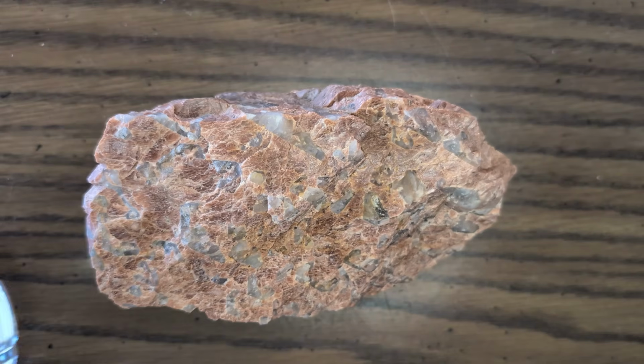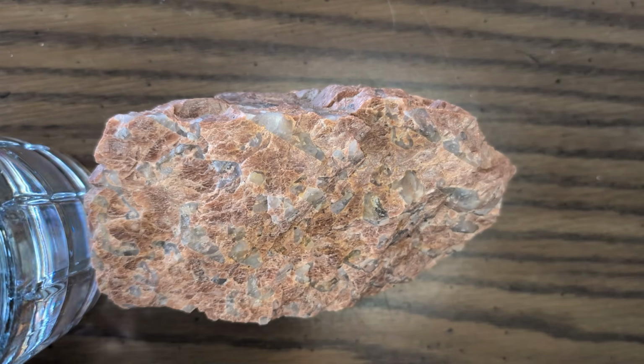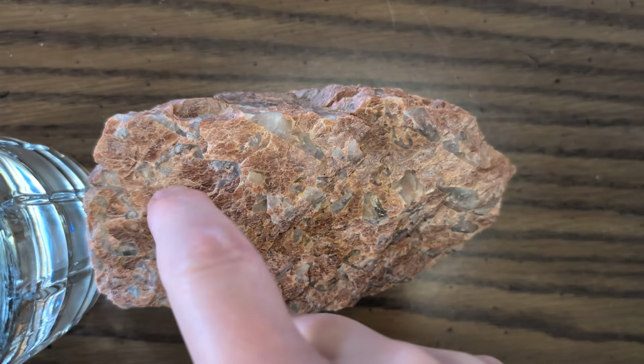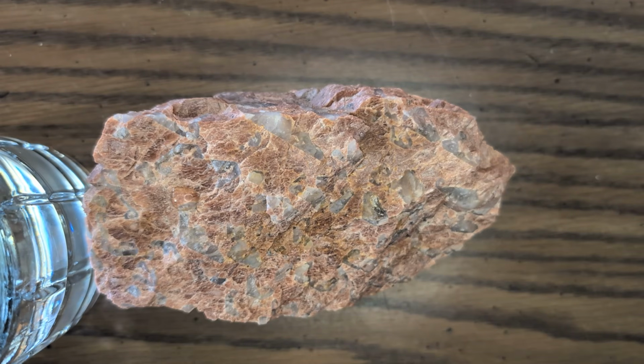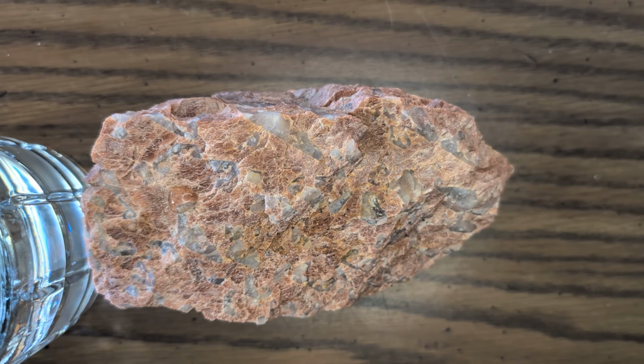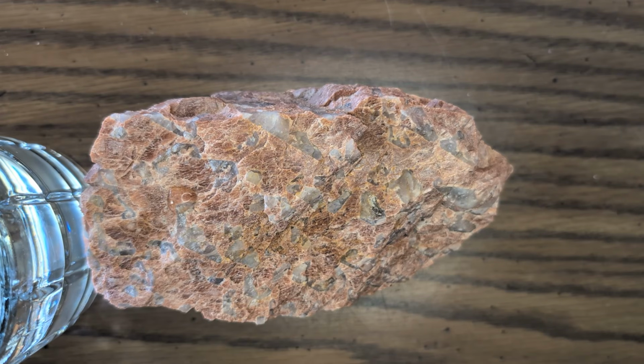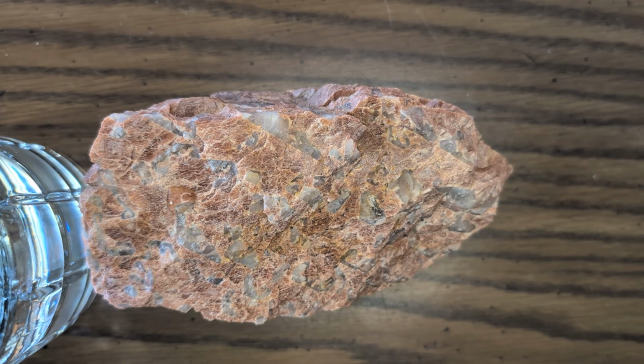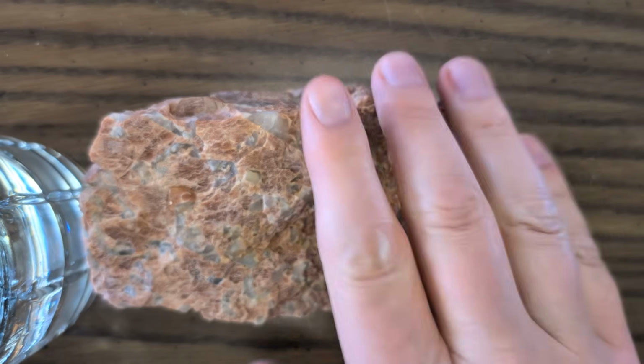Now, for a piece of granite that doesn't have any fractures in it, the hydraulic conductivity is incredibly low. If we place a droplet of water on there and we assume there's no evaporation, it would take about 275 years for that water to penetrate 1 centimeter down into the granite. It is not hydraulically conductive. Of course, if there are cracks in there, then that water is going to flow through pretty quickly and easily. You have a different situation entirely in that case.